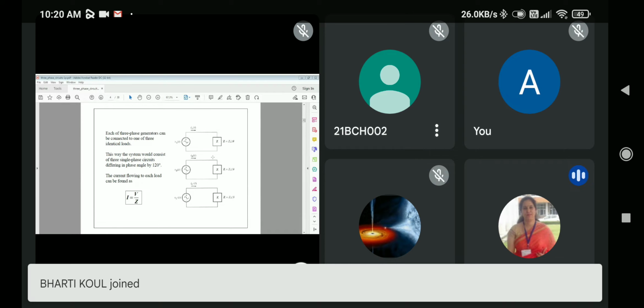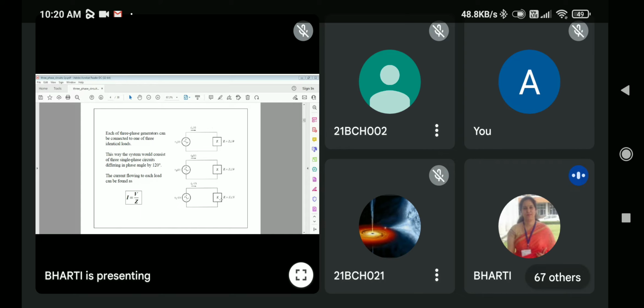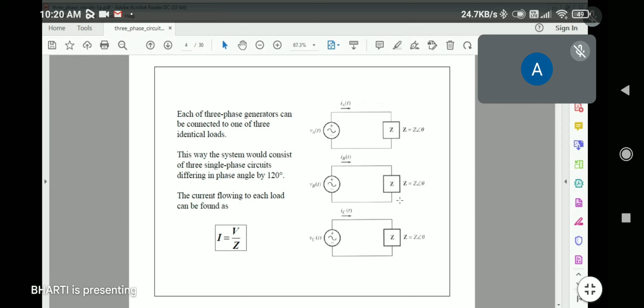impedance. If you talk of again, that will be the same thing. We can say the impedance or the current flowing through. One thing I told you of balanced load. Balanced load, I told you when all the three phases will be having the same load across them. That means the current will be same because Z will be same. है ना? That means I is equal to V upon Z. Okay. So it will be same in all the three phases.